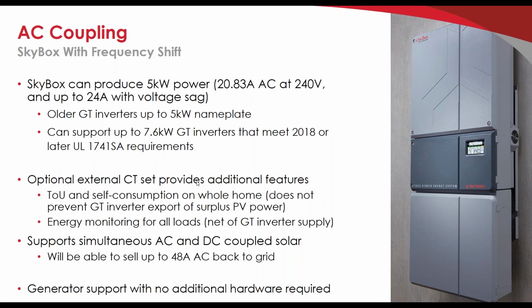So if you have, for example, large well pumps, if you're living off grid, the Radian is definitely the better inverter for you. Yes, you can have some soft start options, and yes, you should size those loads and check out what the locked rotor amp current requirement is for those well pumps and see if it is compatible. But if you know that you've got large surges, definitely look to the Radian first, SkyBox second.